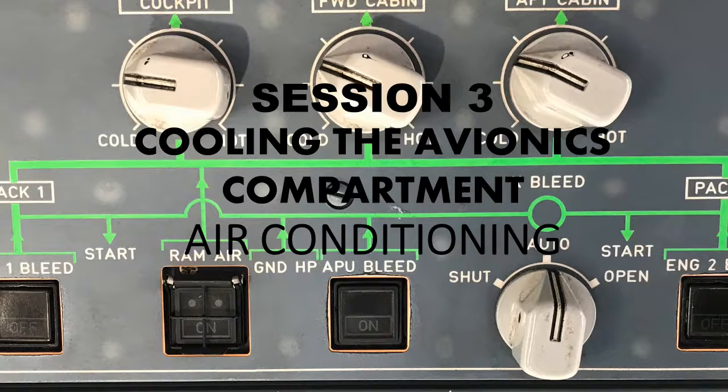And then we also have temperature sensors, of course. The duct temperature sensor we have here is upstream of the electronics rack 80 VU, and there are set temperatures for these sensors. With the duct temperature sensor, we've got the values of increasing temperatures 143.6 degrees Fahrenheit or decreasing temperatures 140 degrees Fahrenheit.